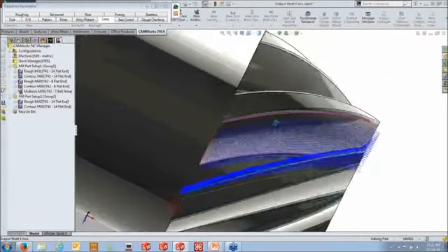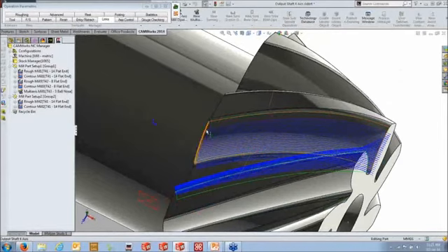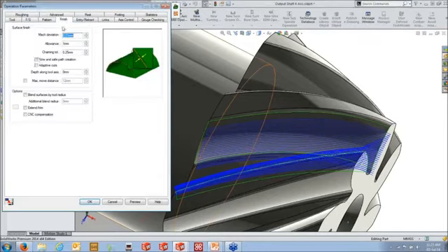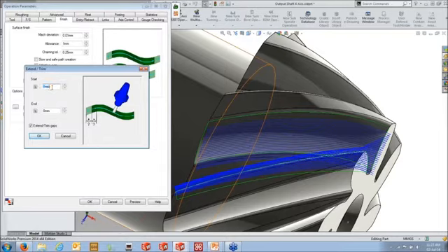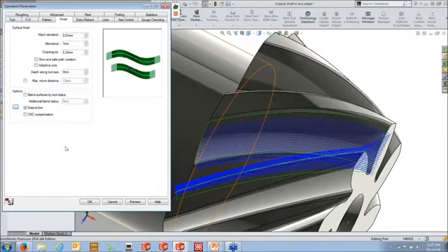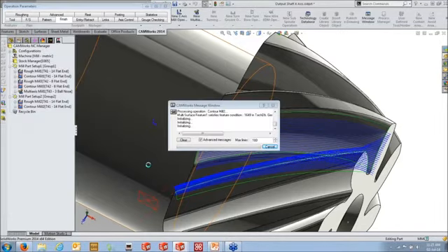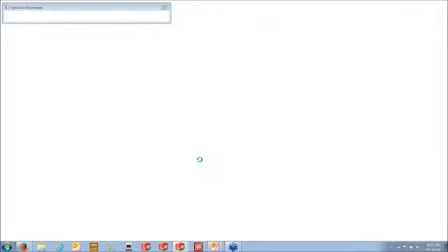Now, one thing we might want to do actually as well is extend the toolpath a little bit further past just to make sure we clean out this material down here. So we can just use our Finish tab and our Extend Trim to go and do that for us here. So if I just put in a positive value in here, we're going to add some extension to either end of our passes there. So that's how we can just make sure and tweak it so it actually extends a little bit further past here.